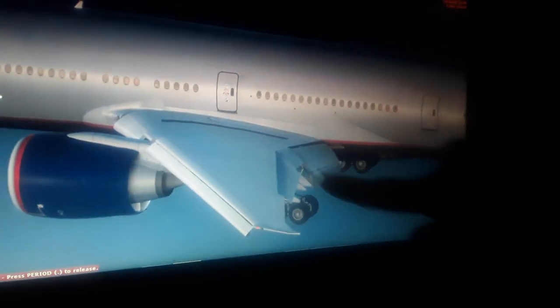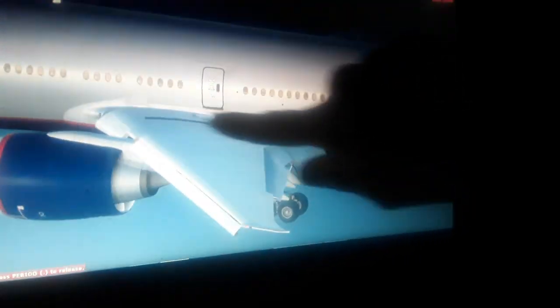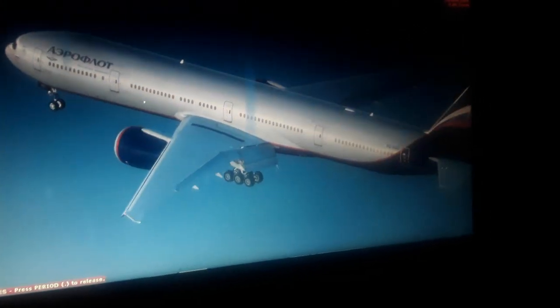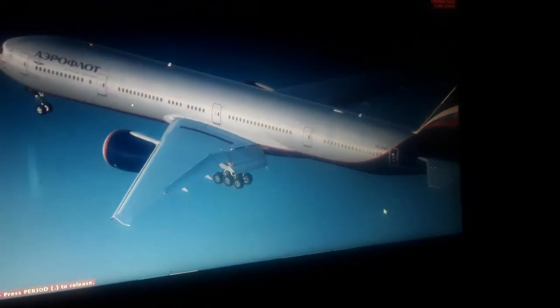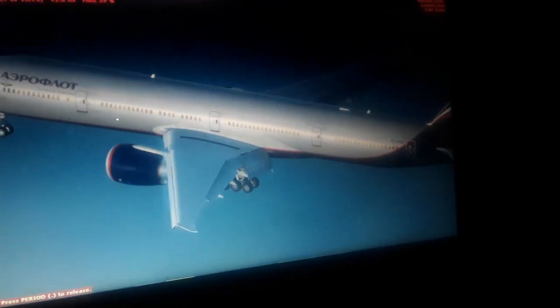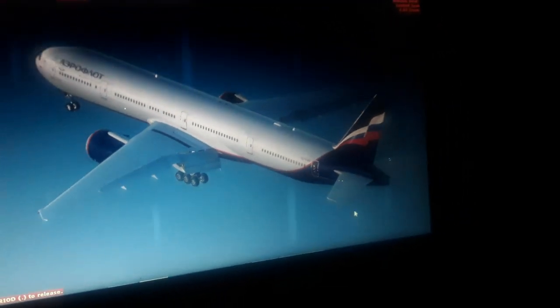Also you can see the top surface of the wing is more curved. It has a higher curvature above the wing, so the airflow of the air mass is moving much faster above the wing. So we have lower air pressure above the wing, which creates an air suction above the wing that sucks the aircraft wings up into the air. So this is the differential positive and negative pressure above and below the wings of the aircraft that creates the aerodynamic lift and forces.